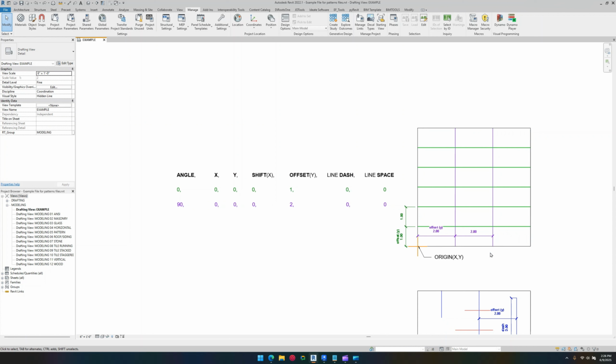And we'll see that in a different pattern later. But know that when you're creating a pattern, the lines are being rotated counterclockwise from the origin point, not clockwise like some people might be familiar with. So that's something to be aware of when you're creating lines. So this one you can see, again, just a continuous line pattern, crosshatched.